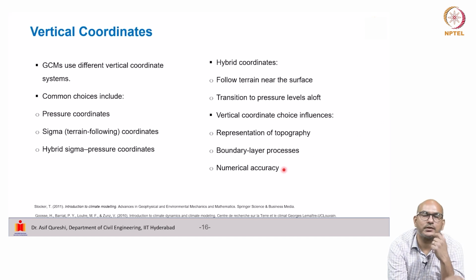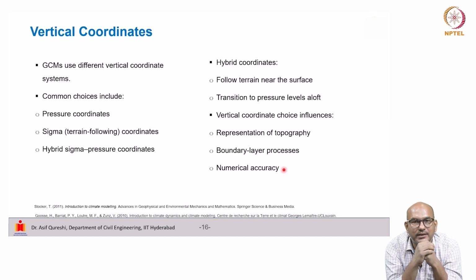accuracy of the simulation. So, in all these, you are hearing numerical accuracy a lot of times. That is because in all these models, we often have to make a compromise between the time step of integration and the spatial resolution. We have also seen in the previous week that many numerical schemes will have a numerical diffusion term, which is actually an error introduced by the integration, and our goal is to have that be as low as possible.